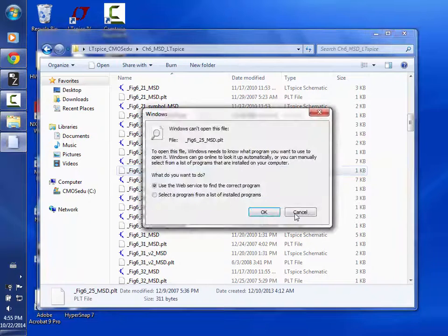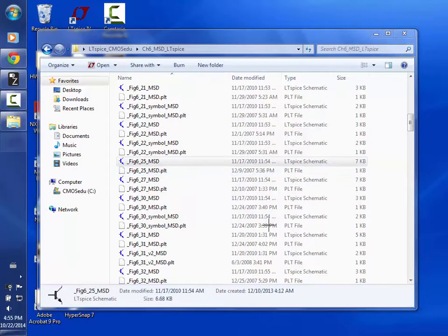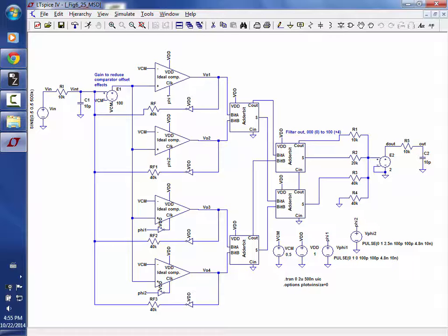Okay, so if you look here, here's the idea. I'm going to take a single input path, one sigma right here, and feed it to the forward path. So the forward path is basically all of this, and once I get to here, it's all digital, right? So the forward path goes from here to the output. I'm going to take advantage of the fact that the forward path can make mistakes and be sloppy. Does everybody get that? My A doesn't have to be precise. My feedback paths are the ones that are critical.